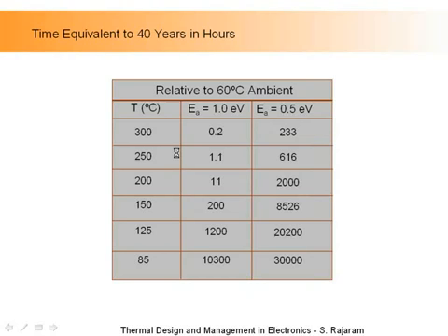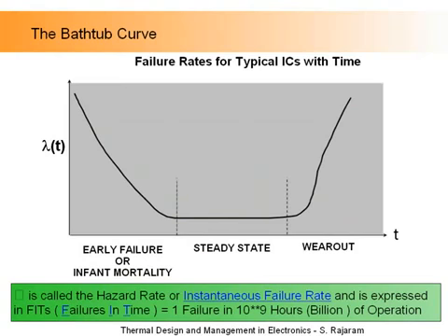Okay, so one more thing before we get into actual thermal design or heat transfer of electronics. Remember I told you we measure lambda, the failure rate of a product. Typically what is done is that you take a sample of product, let's take about 100 devices, and you power them up at a high temperature. And then you monitor them over time and you measure the number of failures.